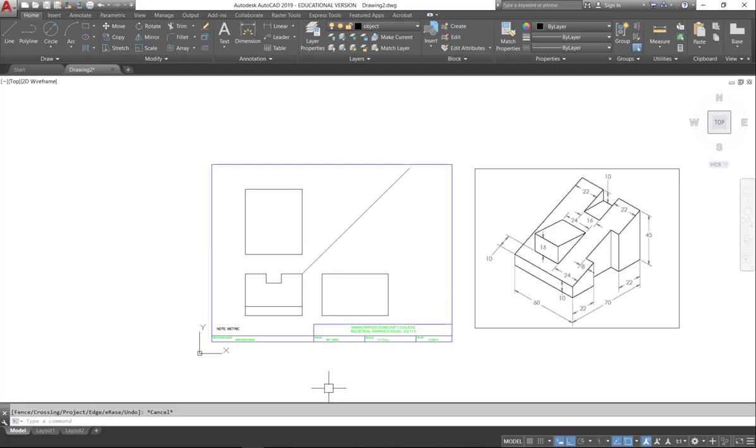That's about all that I can draw at this point in the front view, because I can't draw this little lip sticking out. I'm going to have to get that from the right side view. So what I do know is that this angle is going to go from that 10 all the way up to the corner. So I'm just going to project my line over, and draw a line from the intersection up to that corner. And then I will fillet this, and I can get rid of that line right there.